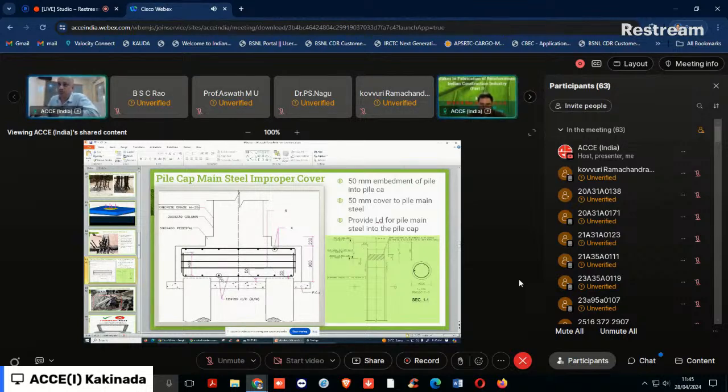And also one more mistake generally come across is the L bend that is taking place here. This should be from the critical section. Suppose this is taken as a concentrated load transmitting in this direction, and this is the probable plane for the critical section for the bending moment, and beyond that it is anchorage. This anchorage length beyond this critical section should be equal to the development length, and that should be maintained. If it is sufficient, we can curtail up to this length, or otherwise we have to extend.